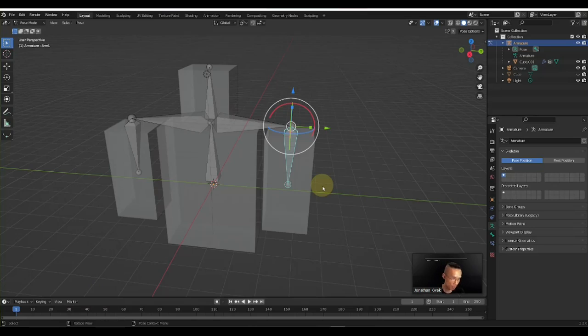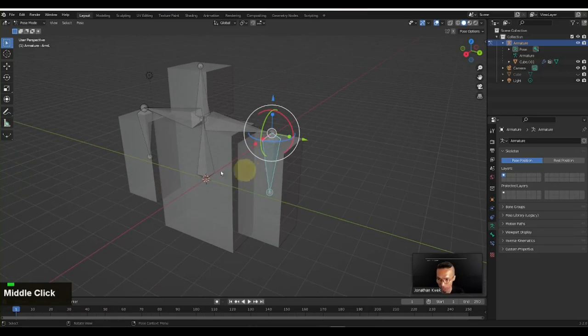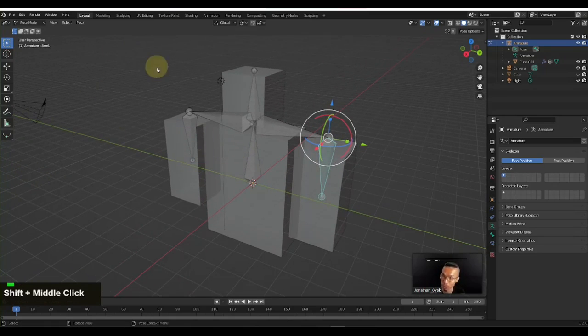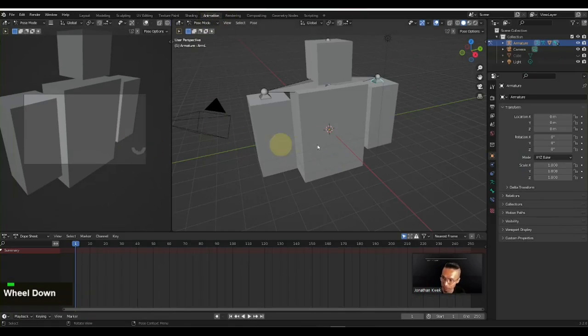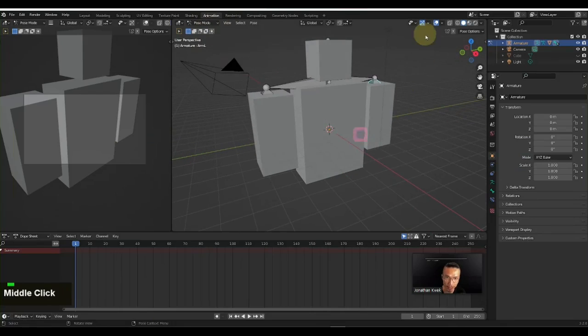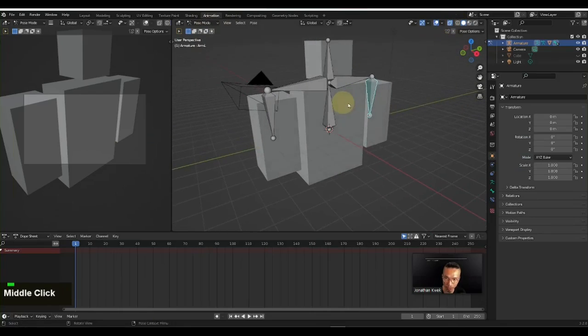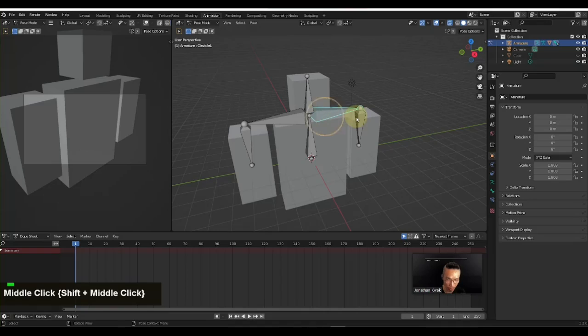With the animation process, what we do is go to the animation timeline over here. You can turn on the see-through mode here to look at the bones. So remember, we're not going to touch the mesh anymore. For animation, we only touch the bones. We only set the keyframes for the bones.